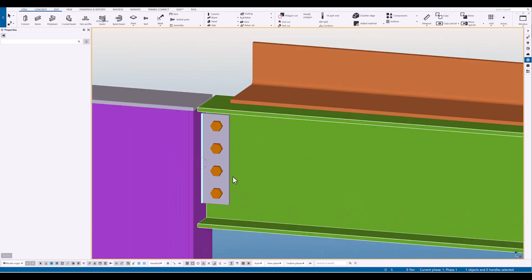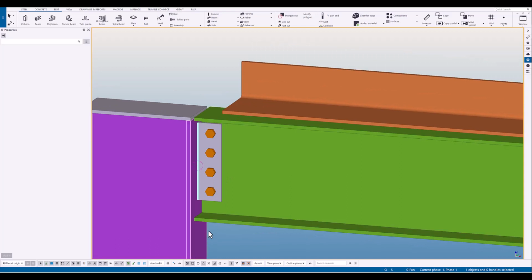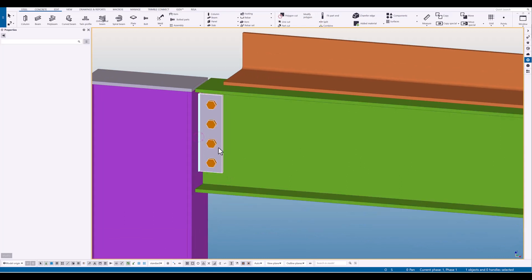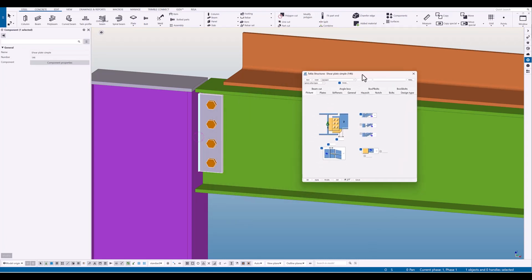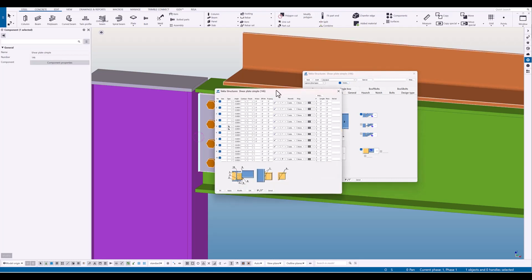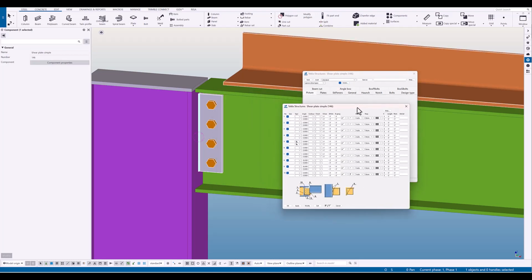Just about every component will have an option in the dialog box for setting the model weld parameters. You can access this by double-clicking the component, then clicking on the Weld button. From here you will see that any weld in the component can be manipulated as needed.